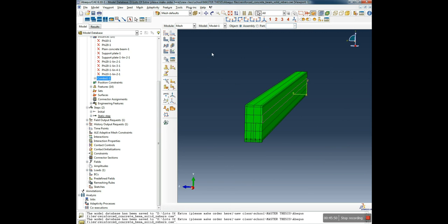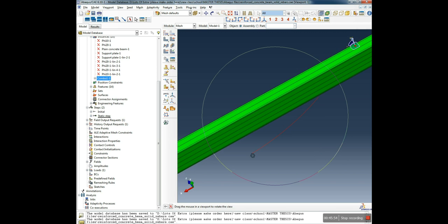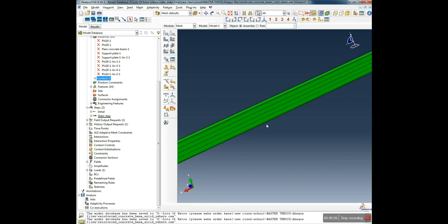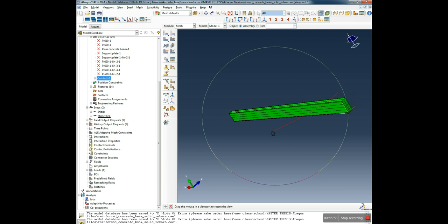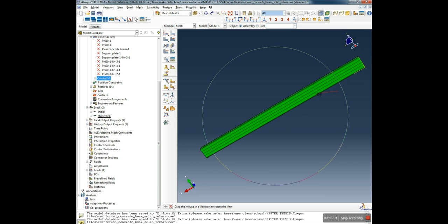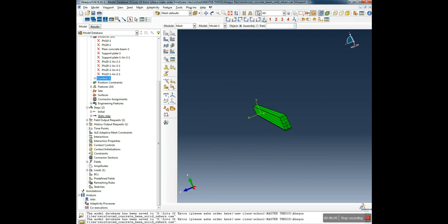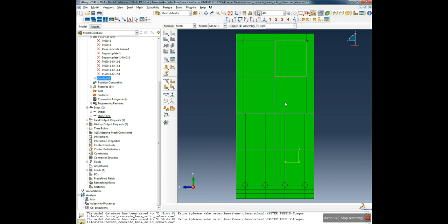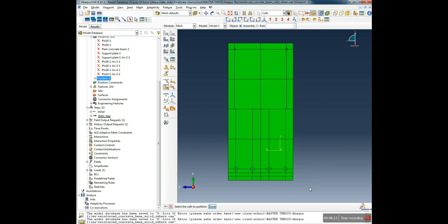And what green means in the mesh module here is that it's possible to mesh it with hex elements. Yes, but a bit of extra work could be also good, but maybe to assign another cutting plane here.